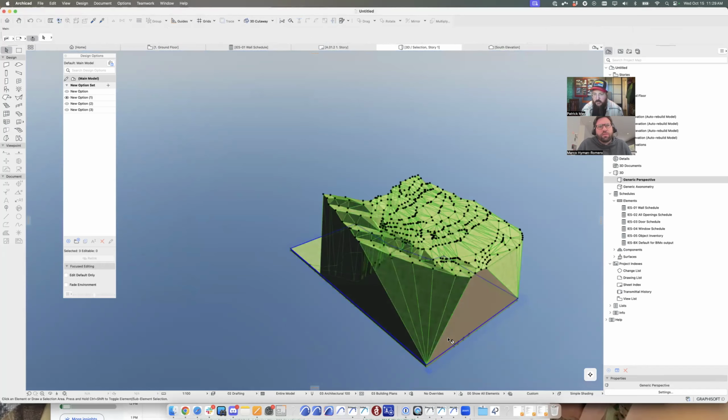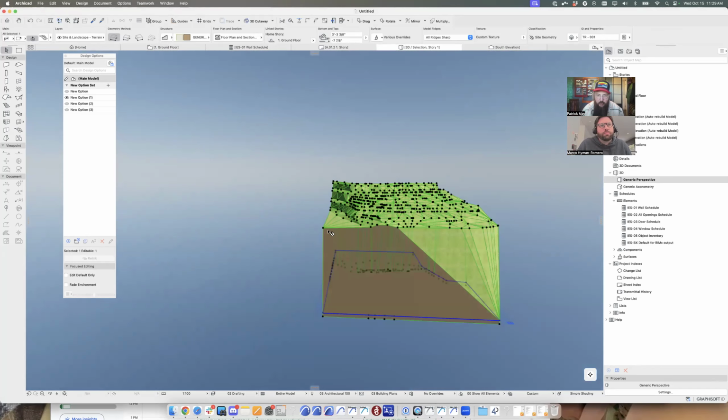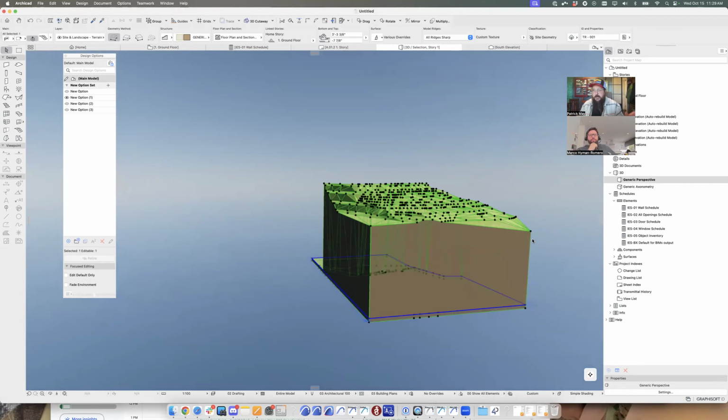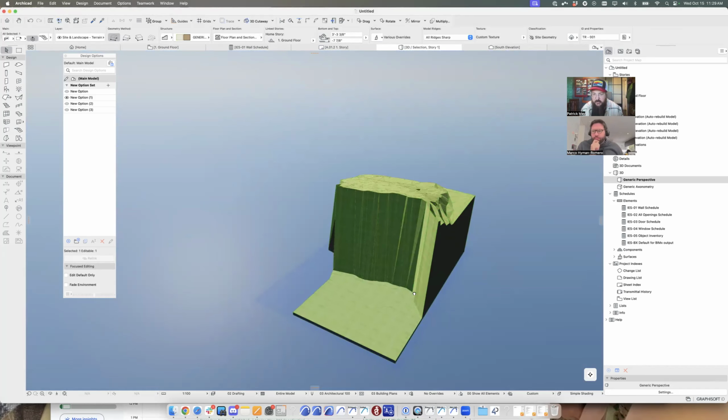Oh, okay. And there's always going to be some points along the edges where you're going to have to sort of massage this up. Usually when you're at the property corners, unless the surveyor's giving you property pin heights, which some surveys will sometimes have, you can elevate those corners to the exact height. But for the most part, you're not usually building right up against a property corner. So massaging it up to what looks good is usually close enough. You can also do this directly in 3D.